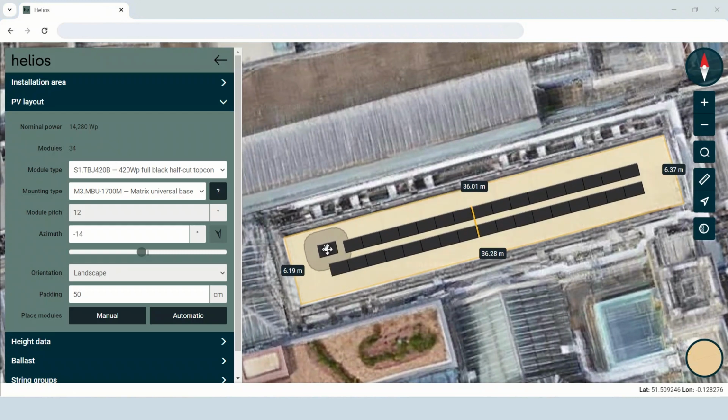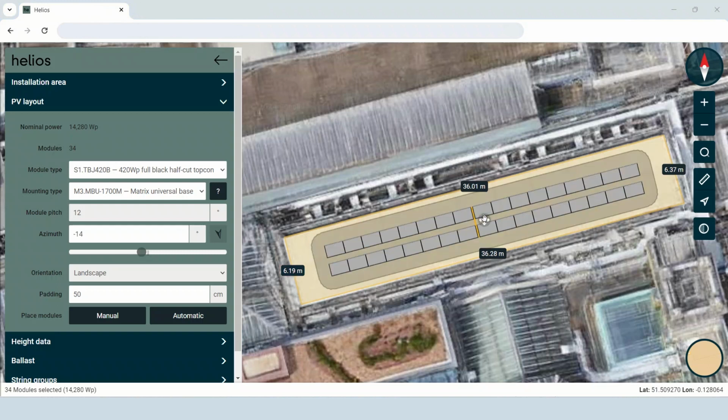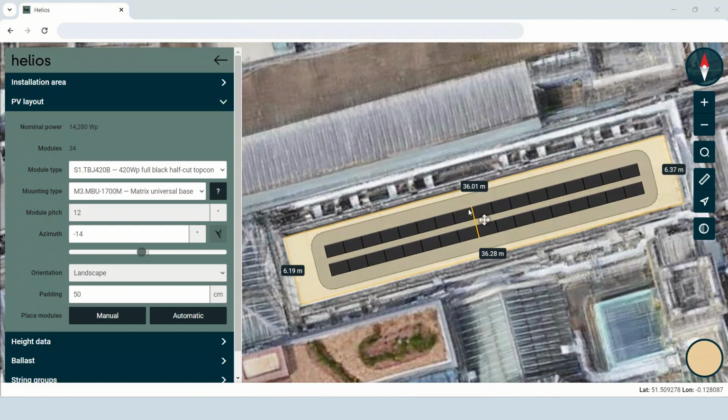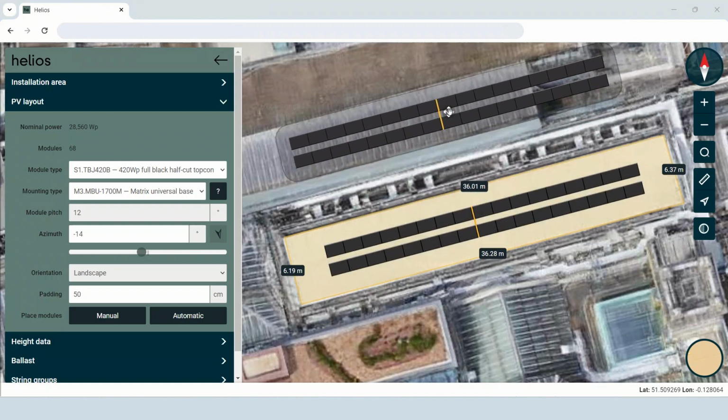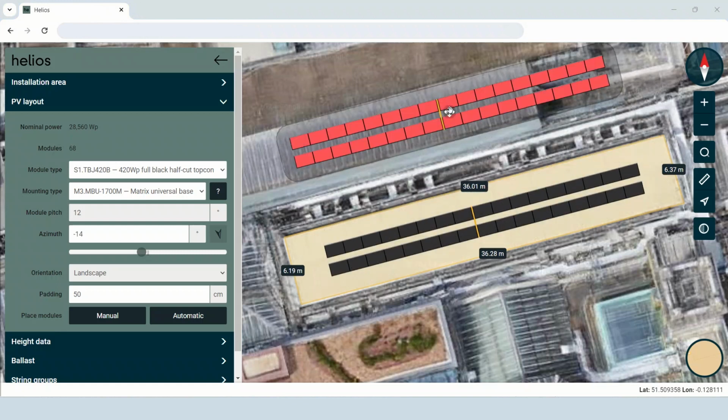This affects, among other things, the mounting layout and materials, as it will no longer be connected. Hold down Ctrl while pressing the move icon to select all panels in that field. Duplicating a field is done by holding down Shift and simultaneously clicking and dragging the move icon. This can be useful when working in a grid.